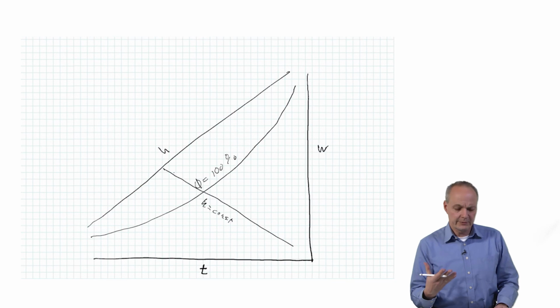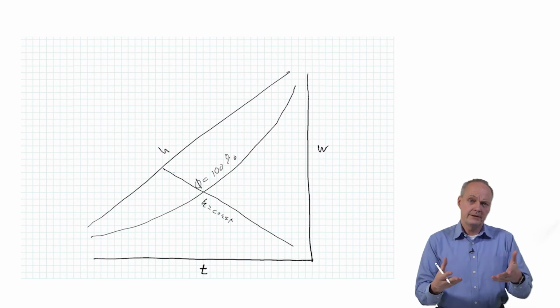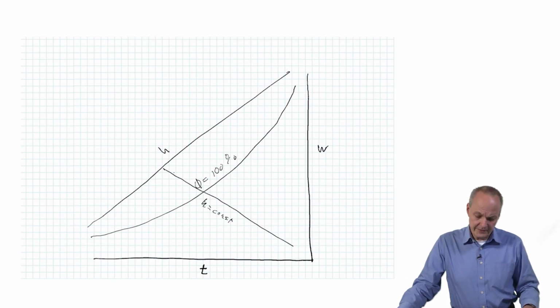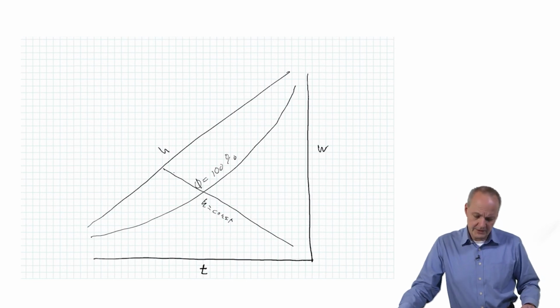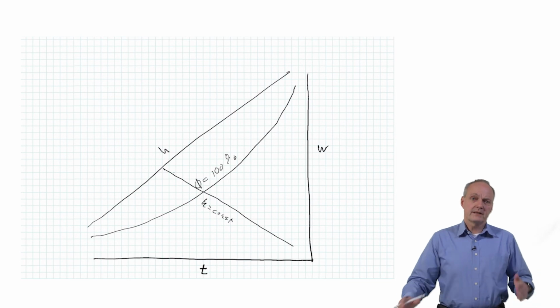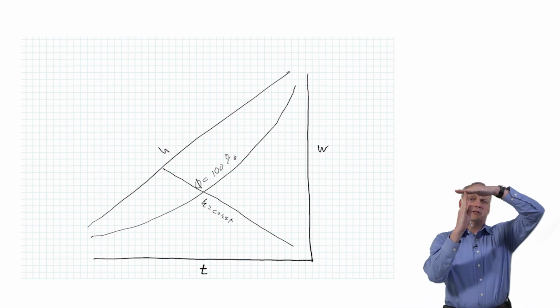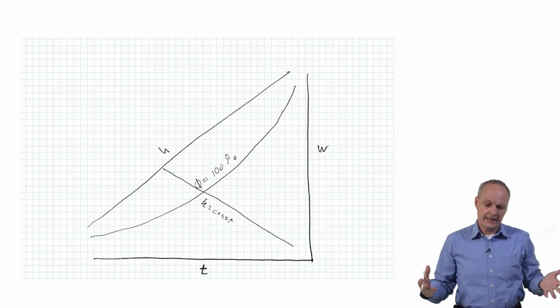But the way the psychrometric charts are constructed is that W and H are the linear variables. That's specifically done for psychrometric problems where the enthalpy and the moisture are the critical pieces that you consider. So in this kind of diagram, even though the axes are not normal to each other but tilted at an angle, a straight line is still a straight line, okay?